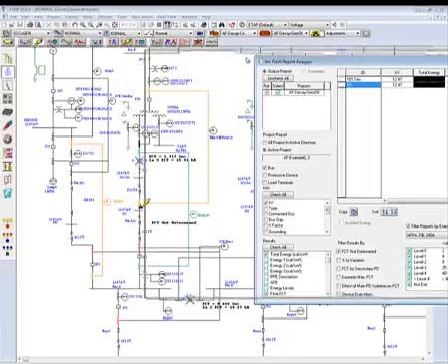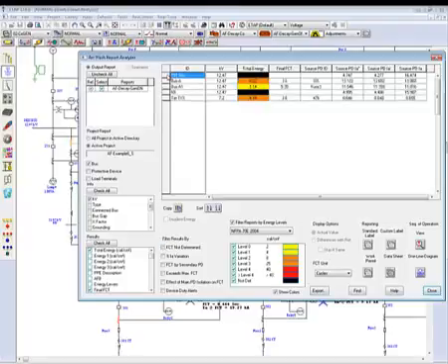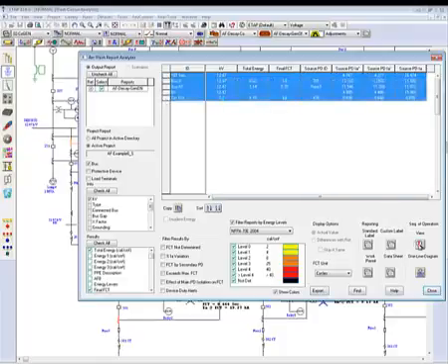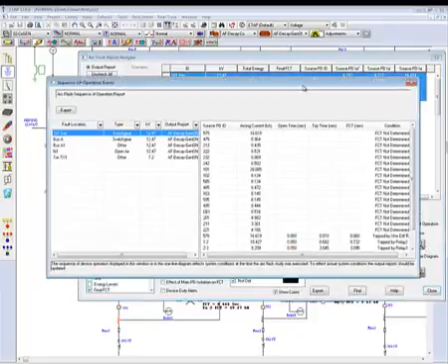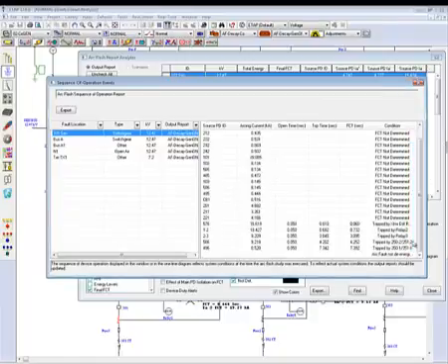Now the Arc Flash sequence of operation viewer provides to you a tabulated report of the one-line animation. You can grab as many buses as you wish by simply clicking on the first row, shift, and the final row, and enabling the Arc Flash viewer and simply launching it. This here will provide to you the full sequence of events and give you the final condition. So for 101 secondary on this switchgear, you see here that the arc fault will not de-energize.